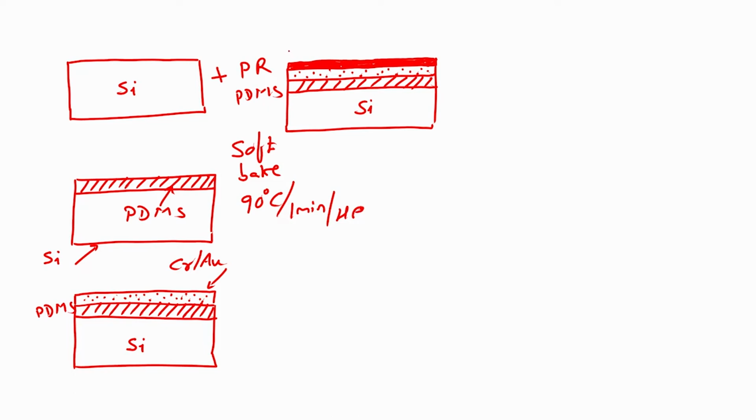After soft bake, I will load the mask to form my chrome gold pattern, and this mask will be a bright field mask.